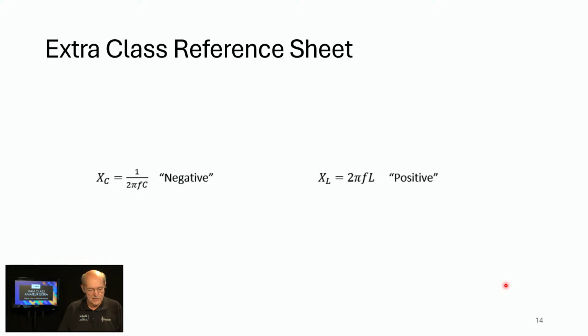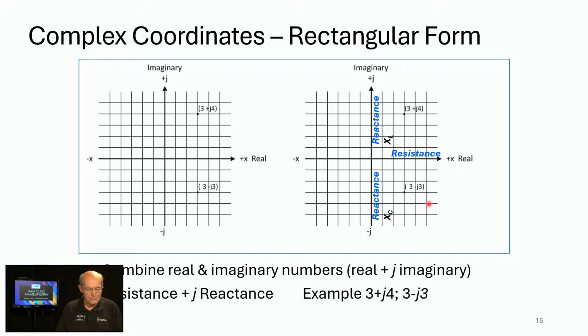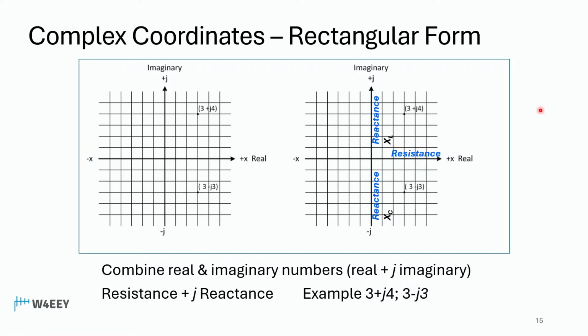And here it is, in case you couldn't see the video, or the calculator cam. We haven't talked about how to work these formulas yet. Well, you know if you worked some of the handouts that I sent you. But the key here is capacitive, negative, inductive, positive on the graph. And we're developing this little by little. So, as I said, reactance is shown on the y-axis. It's indicating positive J, minus J. Resistance is shown on the real axis, or x-axis.